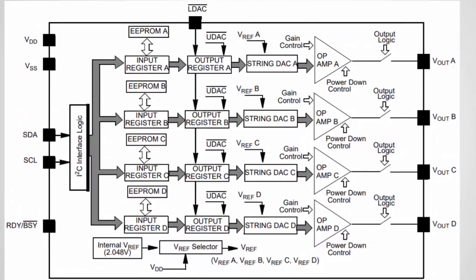Okay, here is the slide I left off on in part 1, and we just went over some of the features in the MCP4728 architecture. One of the things I point out is modern DAC ICs have a lot of features built in, because really this is the block that makes up the DAC, right? The 4 different DACs. And it has a lot of other features. Most of them I talked about already, but I2C communication for setting up the DAC.